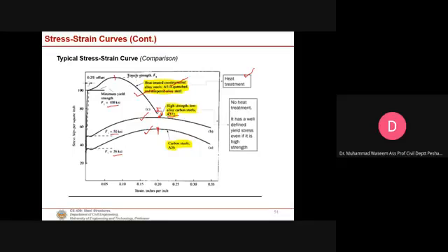So in the A572 steel and A36 steel, the heat treatment has not been carried out, and they have lower yield and ultimate strength, but their yield points are well defined, and the ductility in this material is more. For example, if you use this material, you will have a ductile failure. If you use this material, this will also have a ductile failure. But if you use this material, the failure may be brittle, there will not be ductile failure.